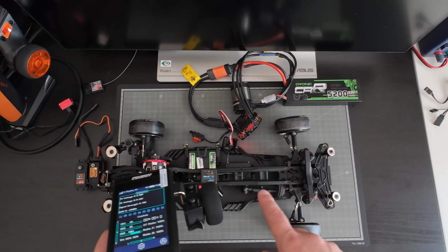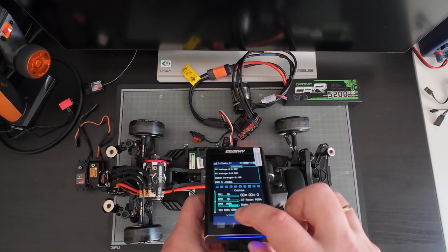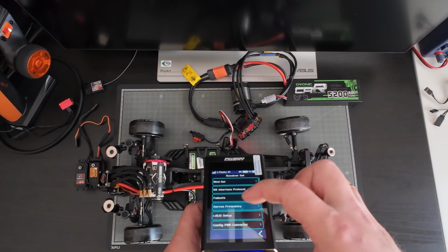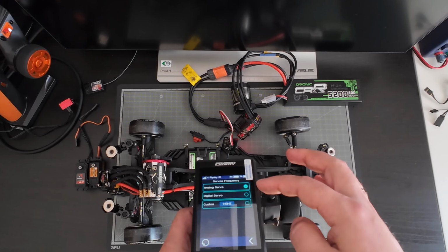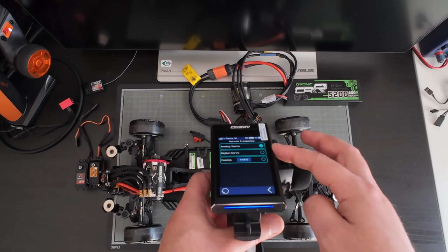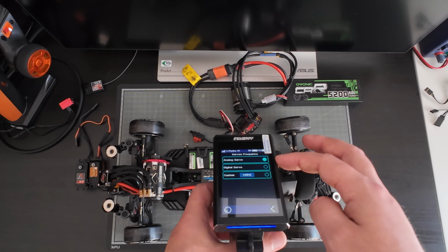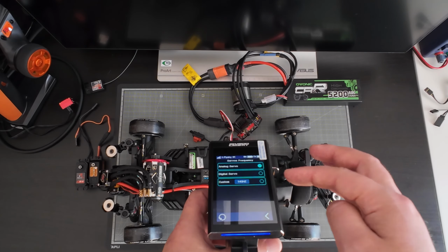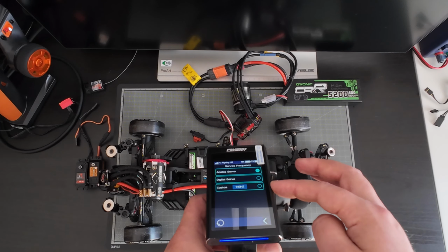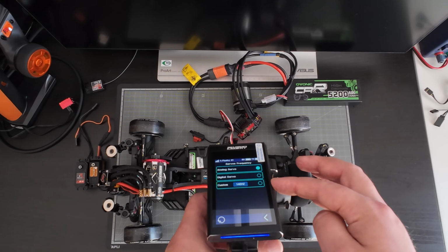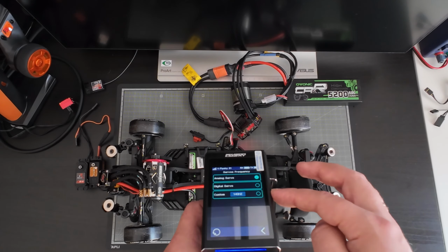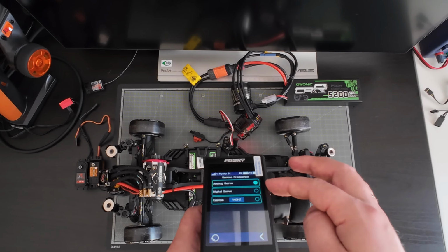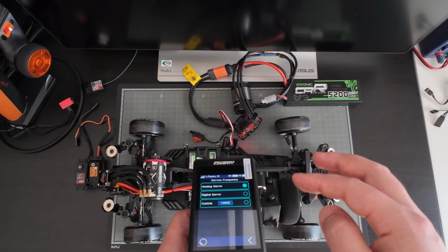Where I can find the frequency for the servo is by going into the settings, RX set, and then we have servo frequency. There we will find three options. Sorry for the reflections. The first one is analog servo, then we have digital servo, and the last option is custom, where we can customize the frequency ourselves, okay? Now it can go up to 400 Hz, which is over 333, which is normally the digital mode these days.